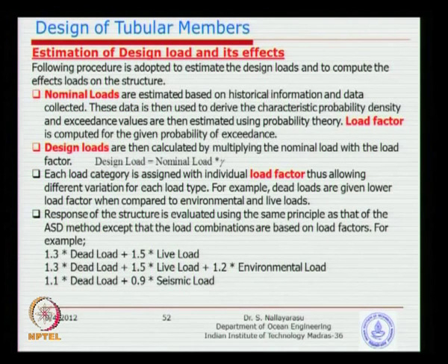Similarly, in the LRFD method, what we are looking at is a nominal load arrived at on a historical basis, but then you develop a system wherein you take into account the probability of exceedance by developing a characteristic probability distribution for each of the variables, and then determine a partial load factor, or load factor, which is proportional to the risk that you would like to take.